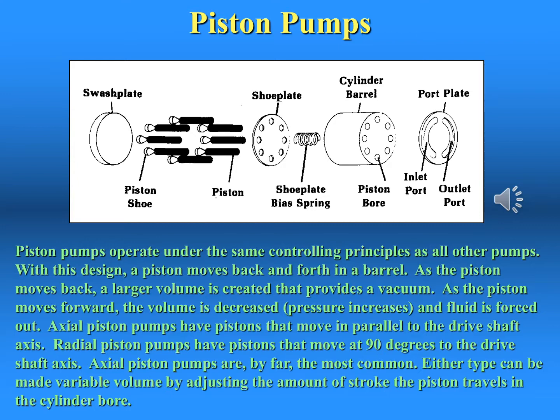The barrel and pistons are prevented from excessive movement by the bias spring, which ensures the barrel stays firmly against the shoe plate. These parts are often sold as a unit for servicing this kind of pump. Almost every manufacturer of these pumps uses the same kinds of parts.